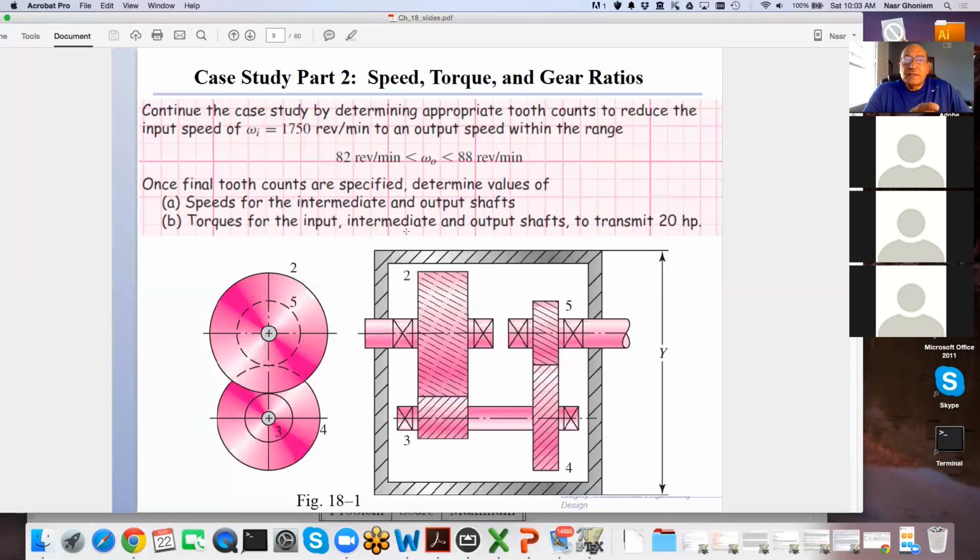And then the RPM and the diameter give us a tangential velocity, and horsepower will then give us forces, and then the forces will determine everything else about the strength of the material, if the gears are going to take that force, the contact pressure, the forces on the shaft, the deflections, and everything else, the rest of the story. So this is kind of a summary.